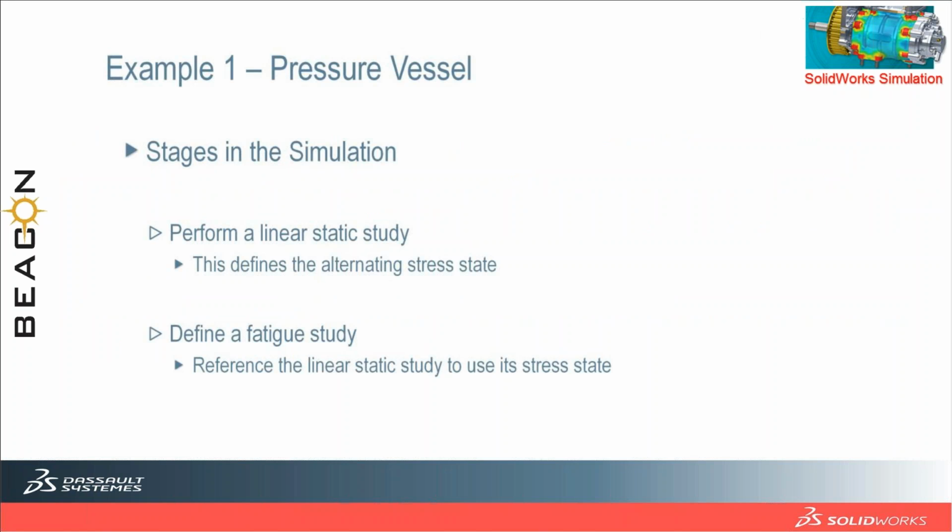First, you need to perform a linear static analysis, which defines the alternating stress state, and after performing this you have to define the fatigue study. What exactly you are doing here is applying the same loading conditions and checking whether it is going to fail for the single application. That may not happen.